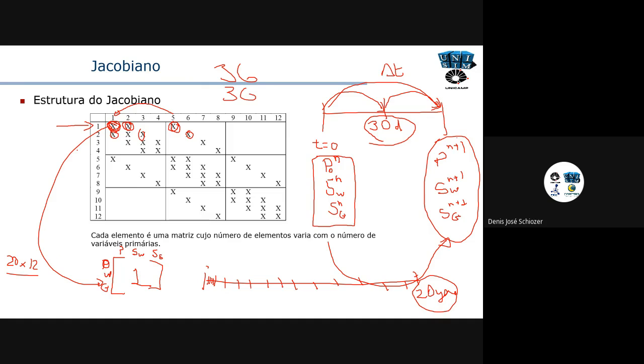It was a very important thing to know, because if I use a time step too big here, sometimes I don't have convergence, so I have to go back and solve everything again. So this takes time in the simulation. And also, if the time step is too big, the solution at the end of the time step is different from the solution at the beginning of the time step. So most of the time, I use more iterations to get to 30 days.